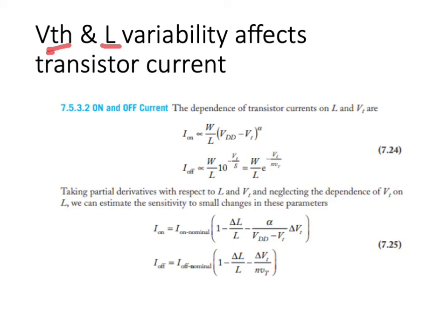As we've discussed in the last session, variations in the process can lead to some variations in the geometrical lengths, the geometrical distances, and changes in the dopant profile, and also the geometrical properties will also change the electrical property, which is the threshold voltage.